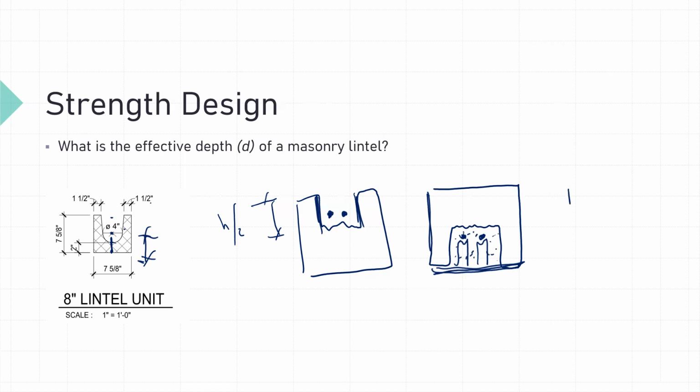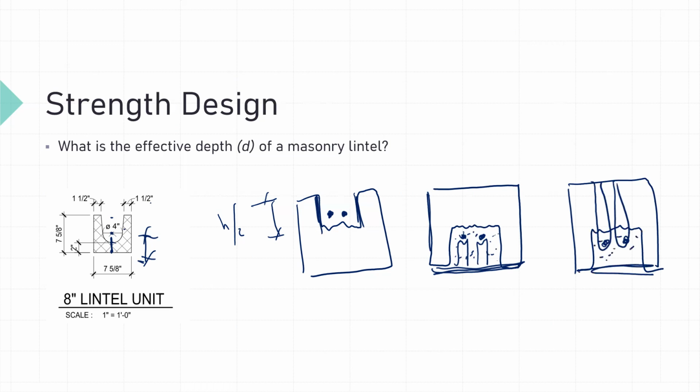We could also, if we had the unit oriented upside down, again, they're going to knock those webs out. We have the reinforcement here. We could use wire ties and wire the reinforcement to this bed joint above it. And again, then shore the bottom here and grout this solid. With the first way, right side up, we can actually put those reinforcing bars directly on the crosswebs.